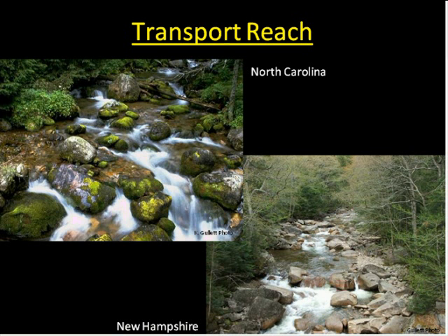Transport reaches are characterized usually by steep gradients, boulder and cobble substrates with pockets of gravel and smaller material, and narrow or non-existent floodplains. Channel morphology is often cascade or step pool types, and the banks and beds are durable because they're made up of big rock or well-embedded large woody debris. Bankfull channel indicators can be hard to find because some transport reaches aren't fundamentally alluvial. Many of these channels are composed of lag deposits left by landslides, debris flows, or glaciers, as in the New Hampshire photo.